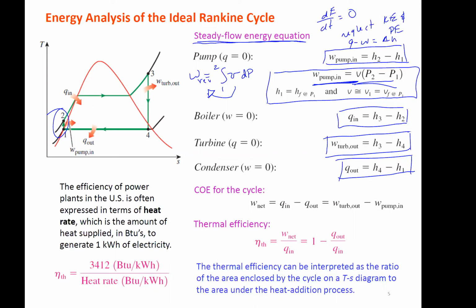Okay. The other thing for pumps is we're going to have the assumption that goes with the Rankine cycle that state 1 right here has a quality of 0. Any inlets to pumps, any additional pumps, would have a quality of 0 because a pump needs it to be a liquid. Okay.